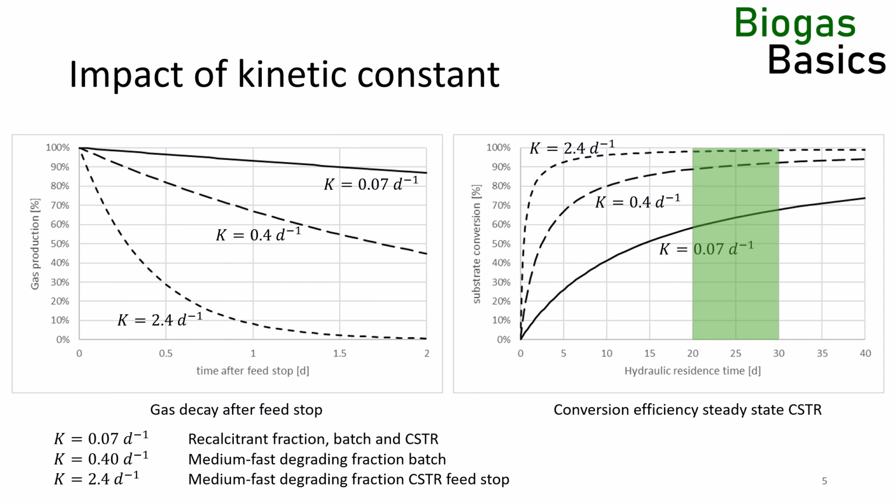To answer this question, we must go back to the overall reaction of the biogas reactor. Substrate plus water reacts to biogas and biomass. In the first order approach, we have ignored the biomass contribution. Substrate simply reacts to biogas, and biomass is just in the background to facilitate this reaction. In reality, some of the substrate also reacts to biomass, and this biomass must be present to catalyze the reaction in the first place. The reaction is in fact a second-order reaction.